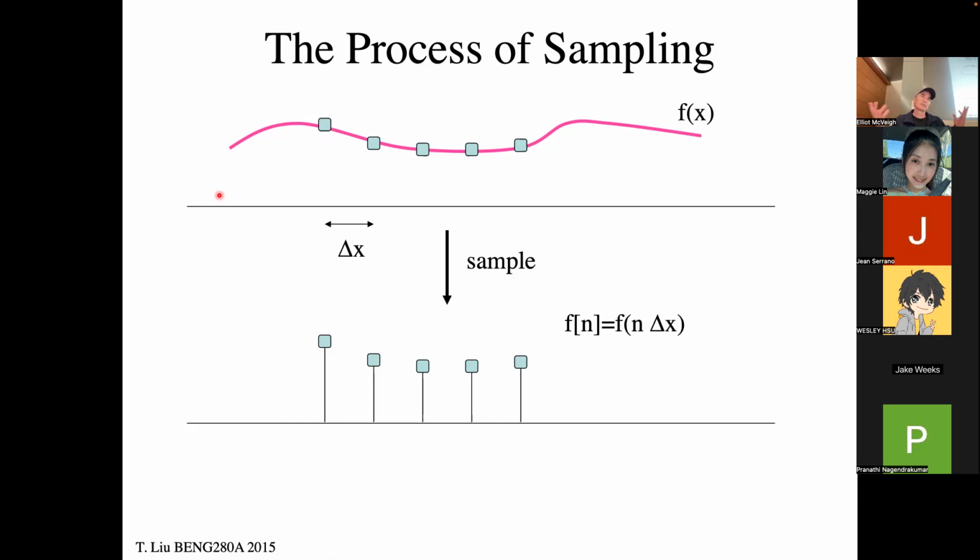It has individual photons, but for us, we could model that with an absolutely continuous function and not have an error. So if we have a continuous function like this, it's the pink line, and we'd like to represent that function with sampled values, we pick our sampling distance, and then we just sample out the values of that function, and then that function becomes this thing.